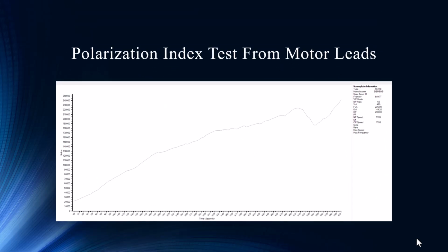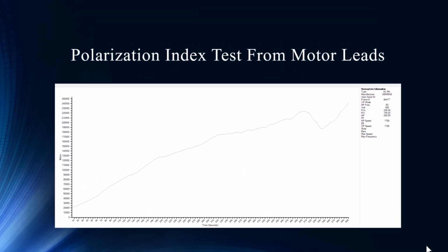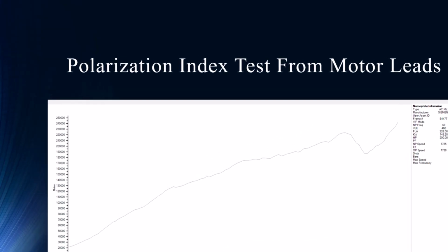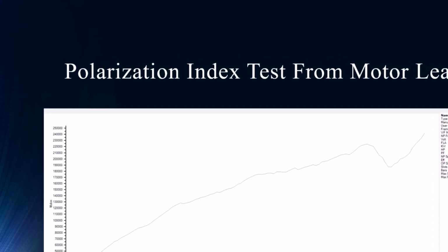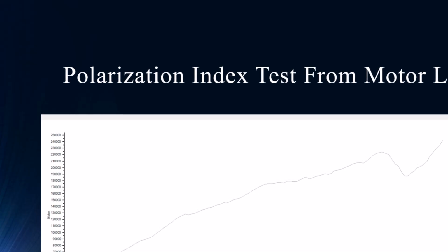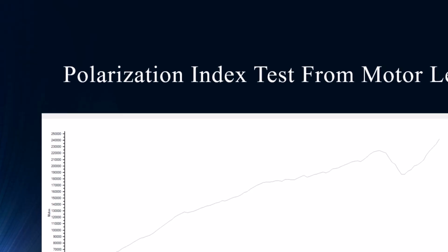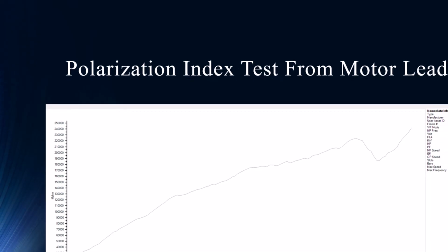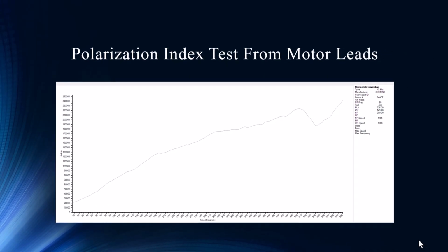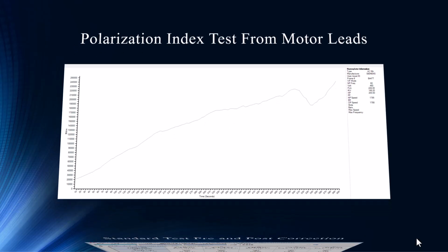So once we fixed it, like we said here, huge difference. You're going from 300 meg to starting out at 20 gig ohms. Yeah, that's pretty substantial, much improved. And it focuses our attention back on the long cable run as the culprit. It doesn't mean we're outside the IEEE minimum, we're still above it, but you introduce opportunities for problems.